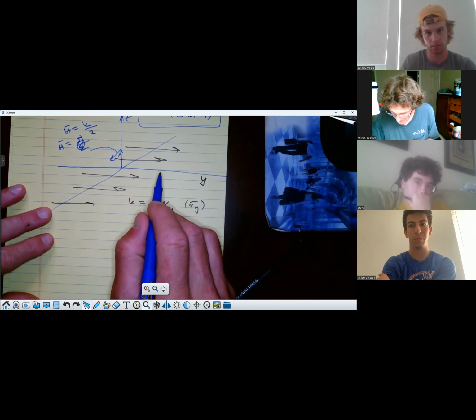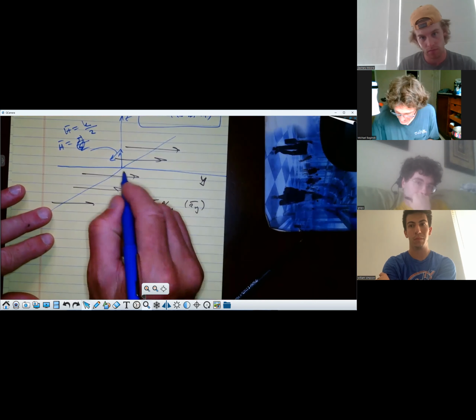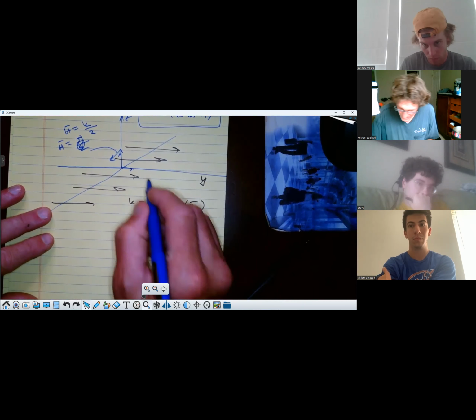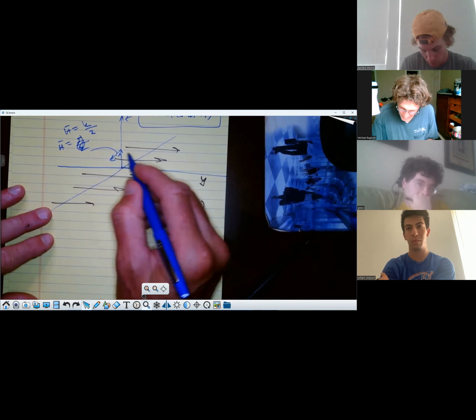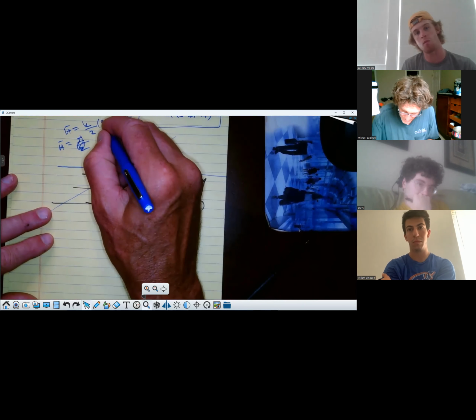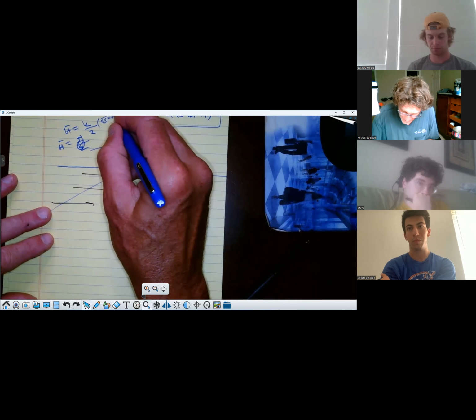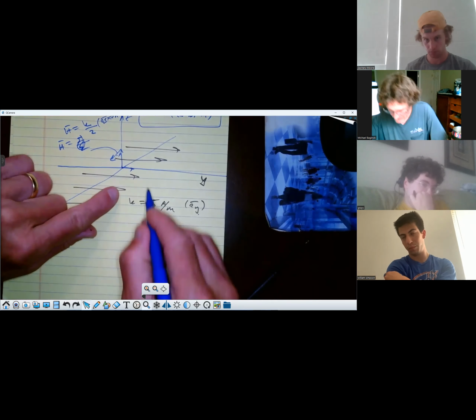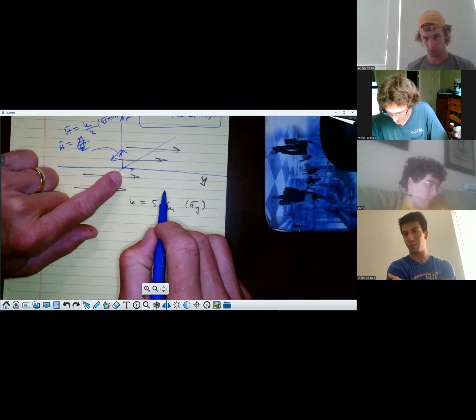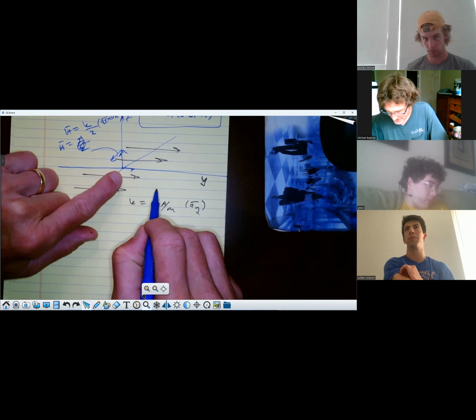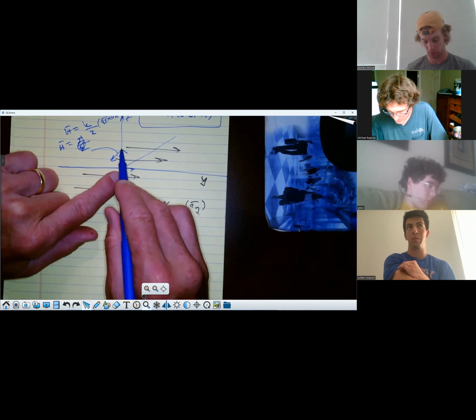Technically speaking, you have a unit vector in the direction of the current. So this direction here would be the unit vector in the direction of current, a_I, crossed into a_N. Now the normal is always pointing radially away from the surface current, from the minimal distance to the point of observation.